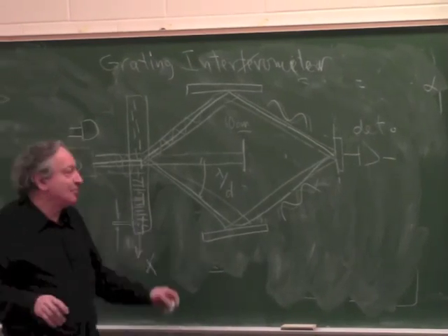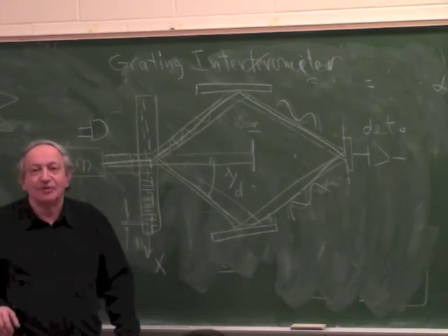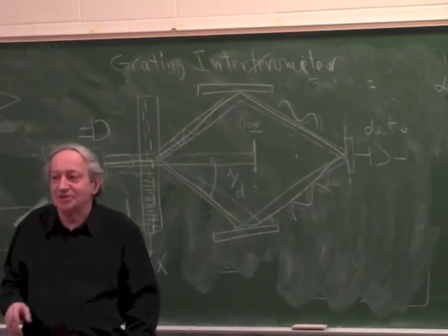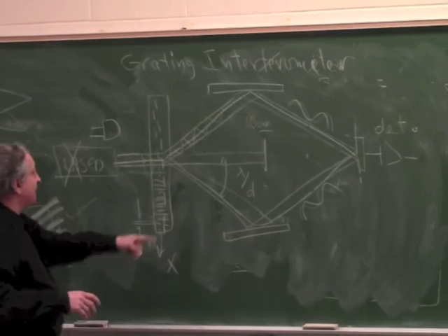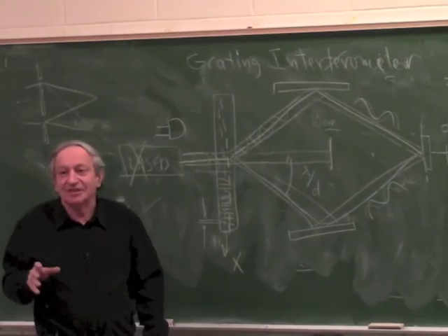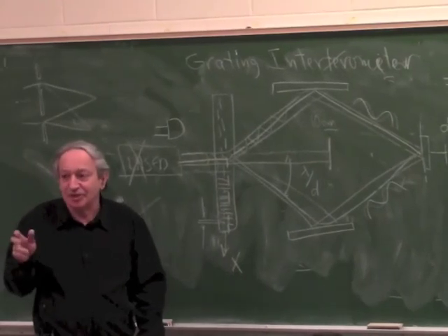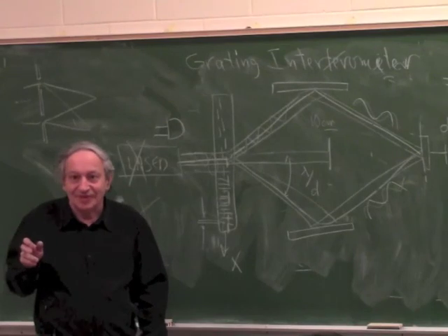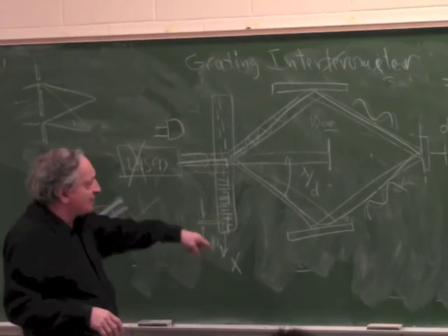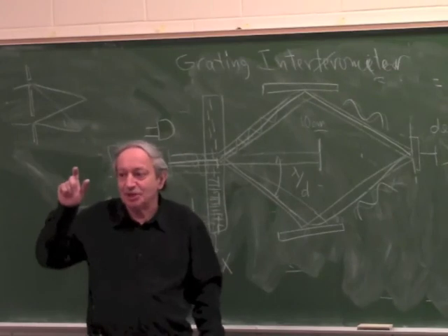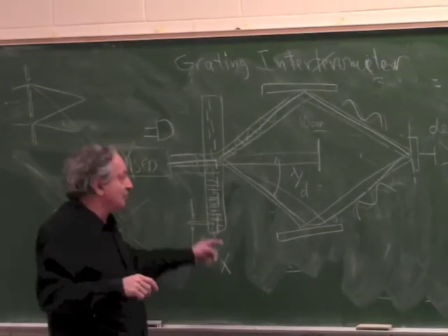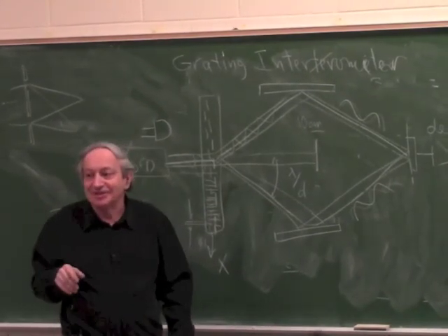So in other words, this replaced the classic interferometer in many position sensors, because this can be made very compact, because it doesn't have a laser, it has an LED. It can be made very cheap. Okay? So these are available in units the size of a matchbox, and with resolution of 10 nanometers, say.